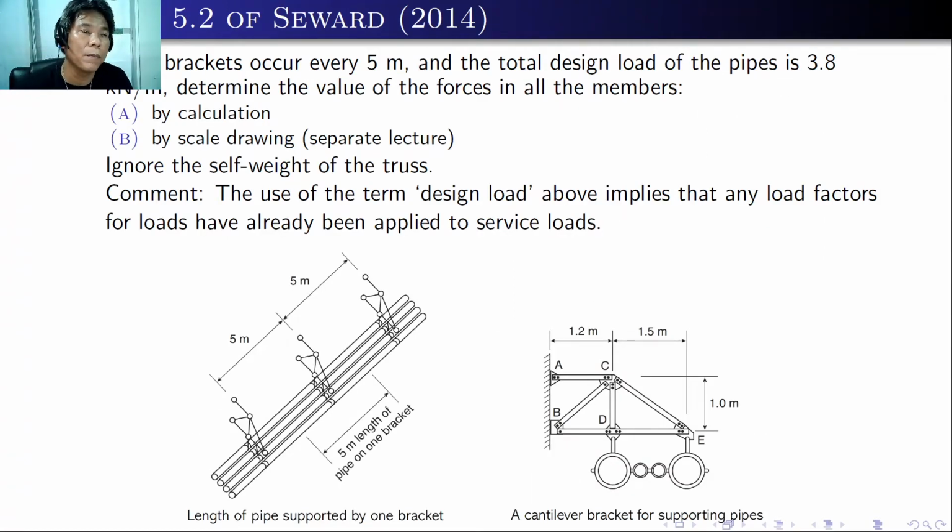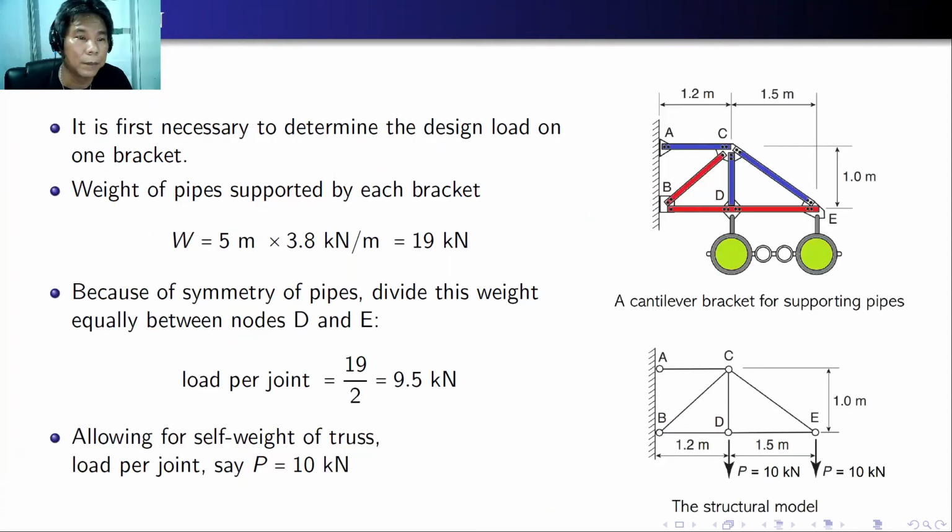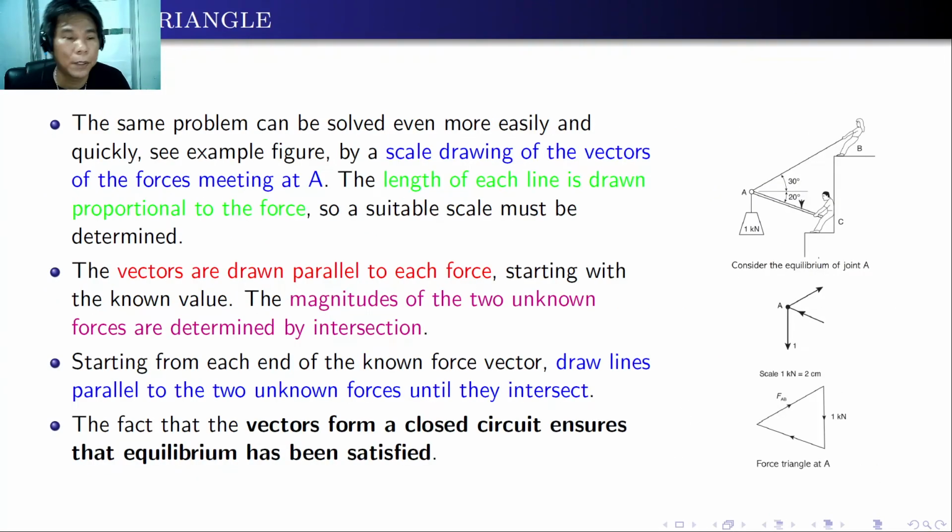So here we have to go back to example 5.2 of Seaward. We talk about this one by scale drawing, or we want to compute this truss using scale drawing. So here we computed the force P. We have shown this one before, and here we will have to discuss first the force triangle. Actually, you have discussed this already in your statics of rigid bodies.